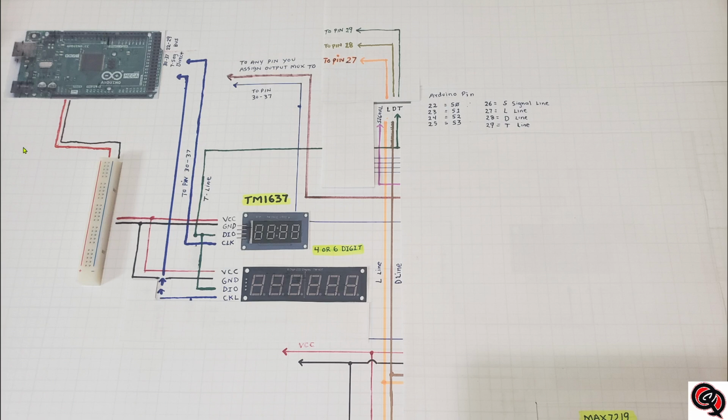But like I've mentioned before many times, if you are going to use a lot of displays, you'll need a different power supply separately from the Arduino. You don't want to be drawing all that power just from the Arduino. But if you're only going to use a couple of them, I would say maybe a maximum of 6 of them, and don't quote me on that, I'm not exactly sure what the limit is. You would have to go in and see how much each one draws, in amps, and then add them all together to make sure that you don't go over, I think it's like 300 milliamps, that you can draw off of the Arduino directly.